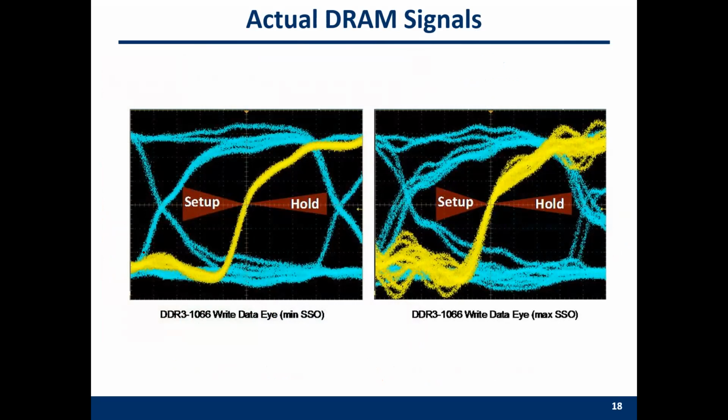This is a data bus signal, changing from low to high, from high to low. You can see that it also requires some setup time because we hope the rising edge can be like this. We hope we have a very steep signal, but actually, it increases gradually and slowly.